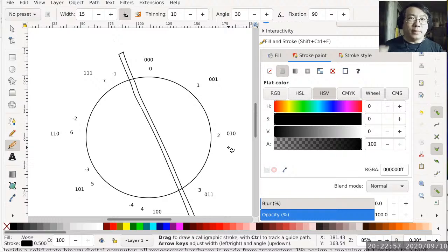The only time it makes a difference is when I ask you, is 111 greater than or equal to 001? Then you need to come back to me and say, that's a trick question. Are you meaning -1 when you say 111, or 7? Because now it changes the output of the comparison. Exactly, Tom is right. Only when you compare do you need to know whether it is signed or unsigned. But for addition and subtraction, it doesn't matter.